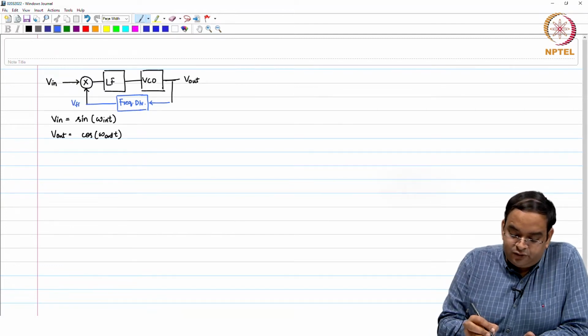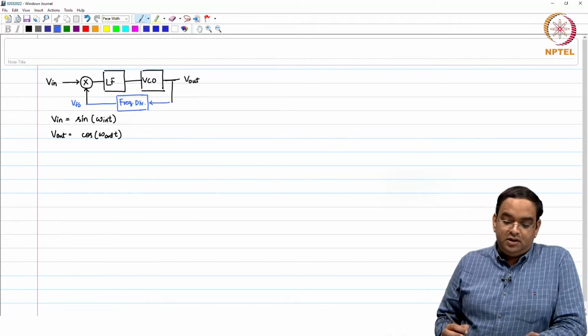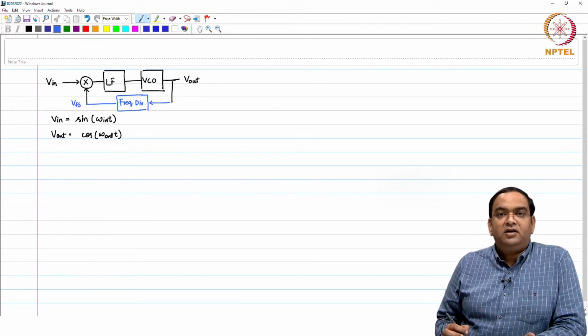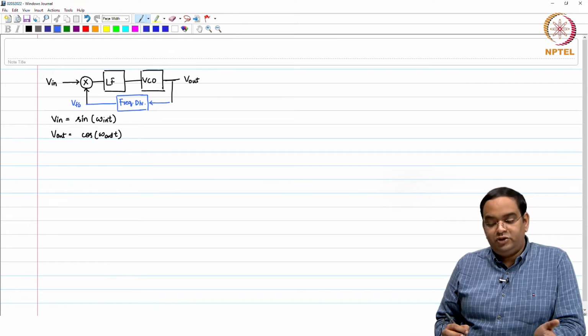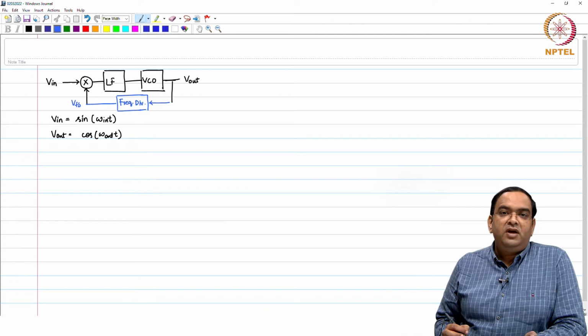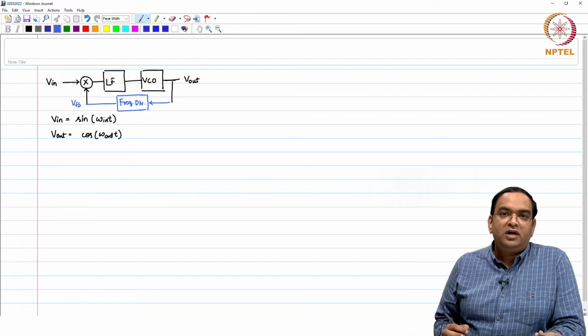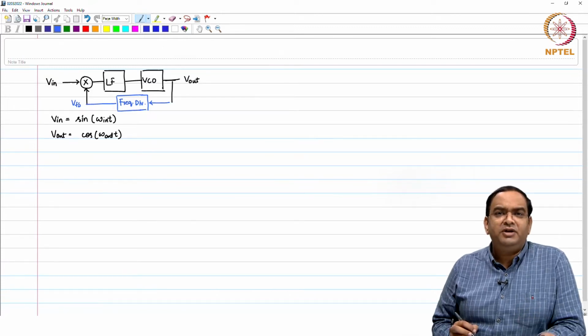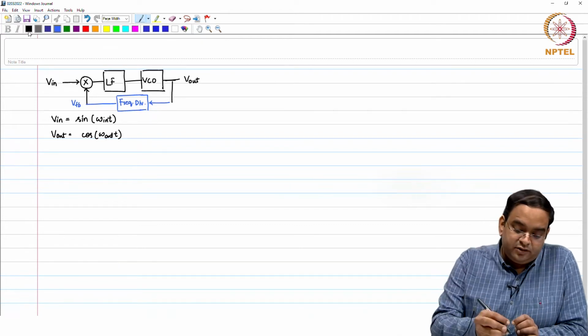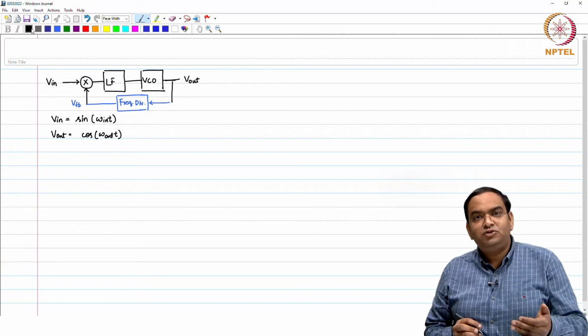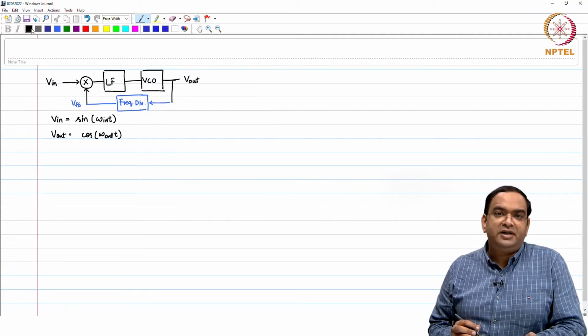as sinusoidal. Now, all the periodic signals which you are going to use in your system may or may not be sinusoidal. As soon as you think about a clock which is used in digital circuits, this particular clock has 0 and VDD, it is a full swing signal and appears like a square wave. So, when you have a square wave signal, using this mixer based phase error detector becomes difficult.